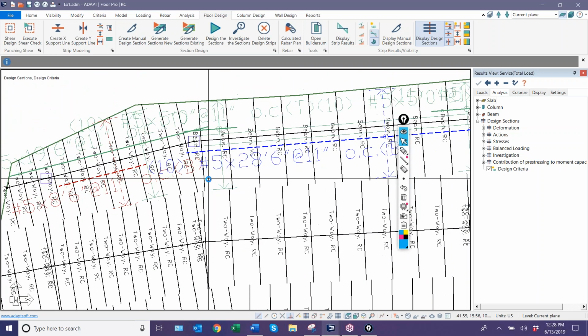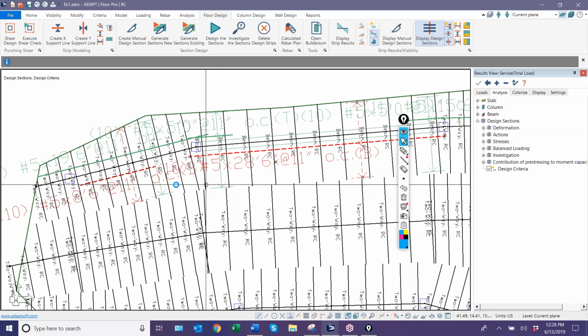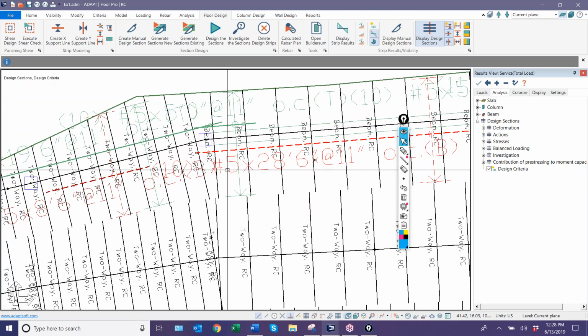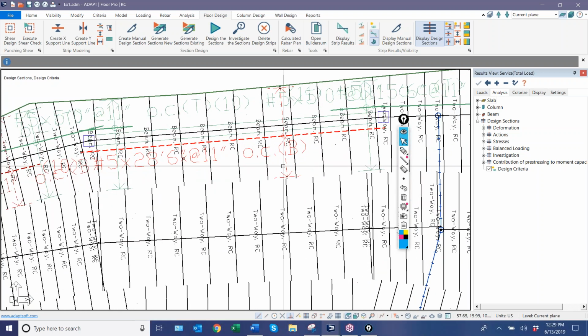First of all, the bottom bars for this beam, what we think are the bottom bars for the beam, are number 5s, but we set the beam to number 8s. And you'll notice that the bars on the bottom actually show as being distributed. So this can lead to confusion. The user then wonders, well, are these bars in the slab or are they in the beam?